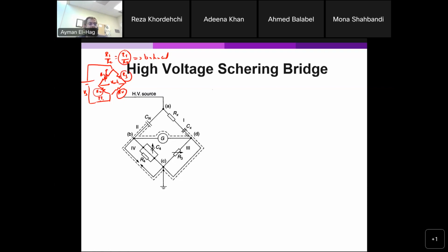Okay, so I bring that resistance here. Most likely the system is not balanced. R1 over R2, which you don't know, is not equal to R3 over R4. This is a random resistance that you have no value for. So then you start to play with R1. You start changing R1 until you make the bridge balanced. Once it's balanced, you know now V out equal to 0.